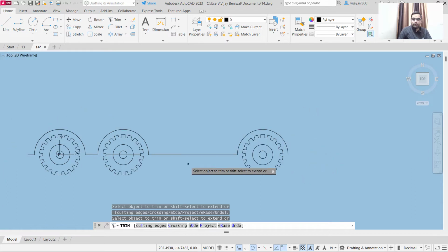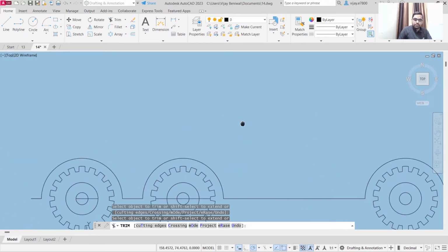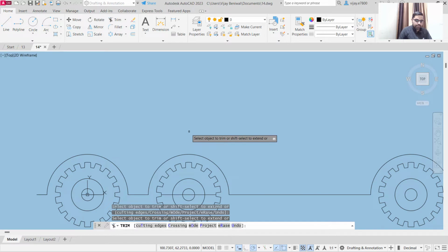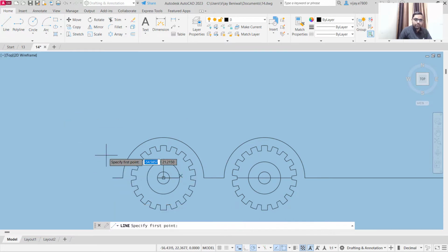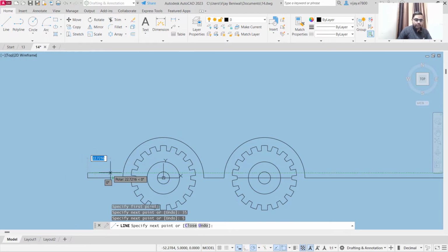So it's done. Now we are going to move towards the other part of this body. What we are going to do is move from this particular point. From this point we need a length of 35 units on the left side. So specify 35 and press enter. Now make sure your polar tracking is on, because it will help you out. You will not have to enter values of angle again and again. So then 20, enter. Now vertically we need to draw a line of 25 first.